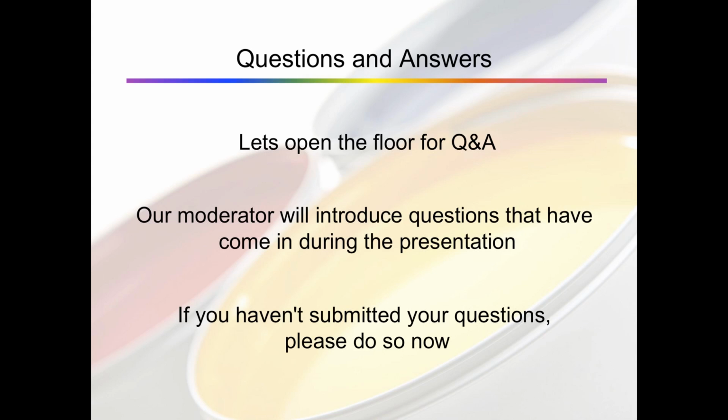But backing is something that you need to absolutely be considerate of when you're taking your measurement, when you have material that is light transmissive. So if the light is going to go through the material, hit the backer, and then come back up, you need to be considerate of what your backer is, because it's going to influence the color measurement that you get.